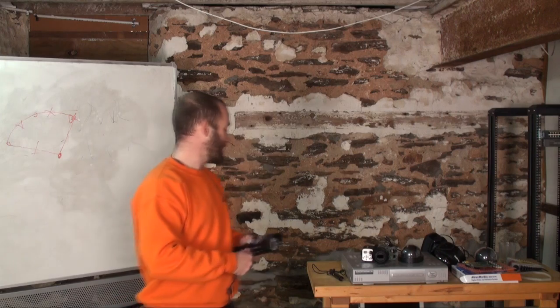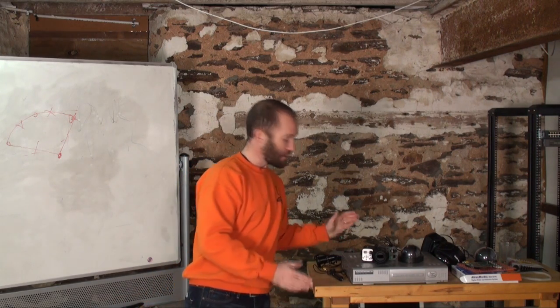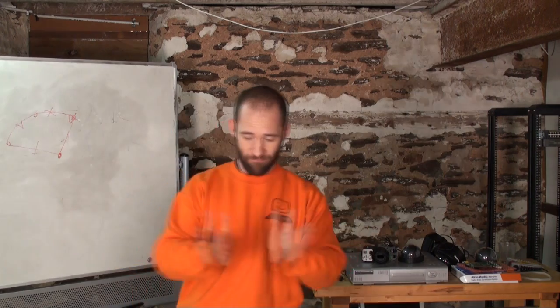Then we talked about wide dynamic range and auto iris. Basically, wide dynamic range is that it can view in lots of lighting conditions. Auto iris means if the scene gets too bright, the iris in the camera will automatically close and try to darken the viewing, so you don't get the washout effect.